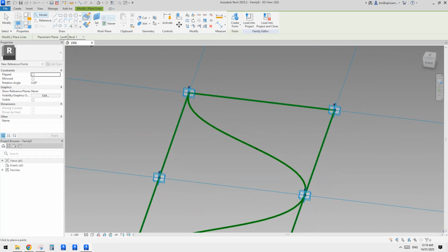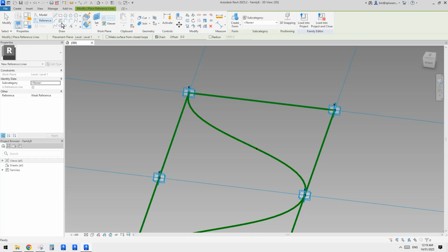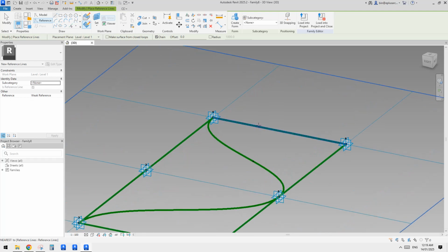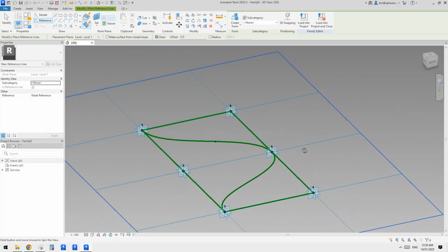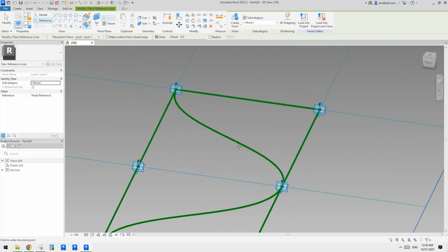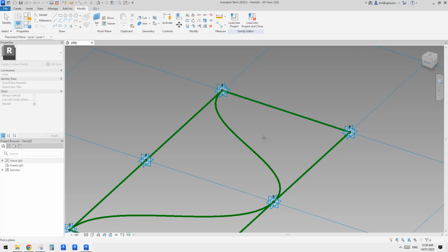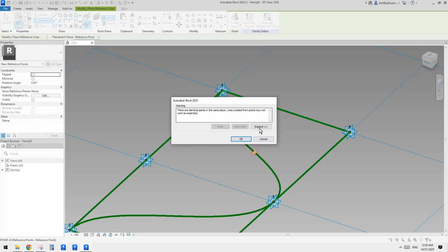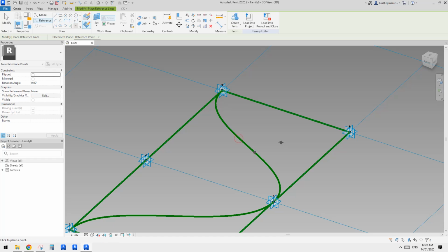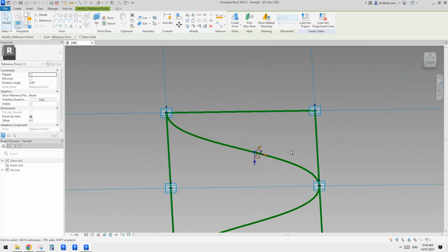So now we can just create a reference line. So actually, maybe let's make it parametric. How about that? So okay, let's select the point instead of directly drawing some reference lines. We're going to use a point, draw on work plane, set work plane, pick the point, so tab, and pick the horizontal work plane on this point, and place onto the point again. So you should see this warning. Okay, so click OK, escape, select the point, and then we can just